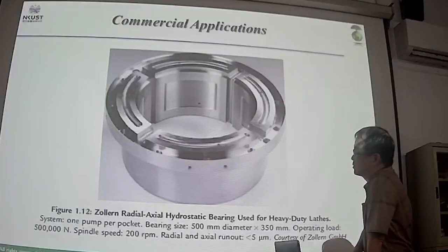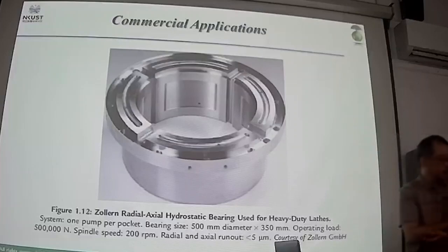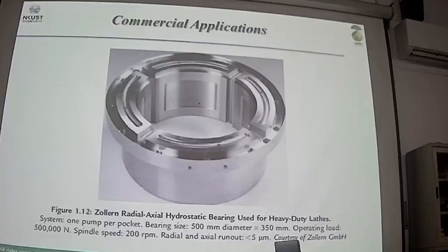So this is typical. Usually if you have a machine tool or rotary table, you need to carry a loading larger than 5 tons or 10 tons. Usually they will make the rotary table by the hydrostatic table. Okay.